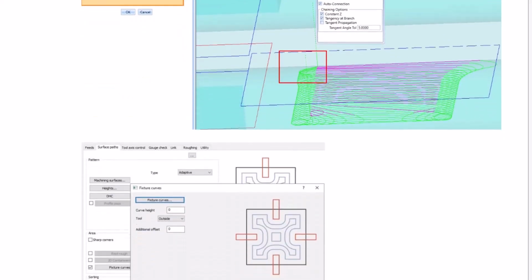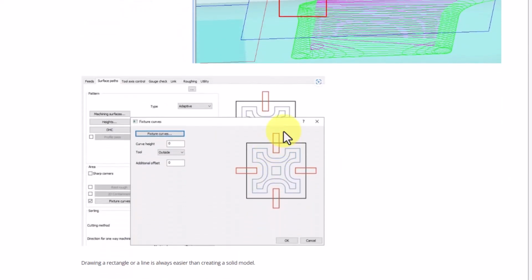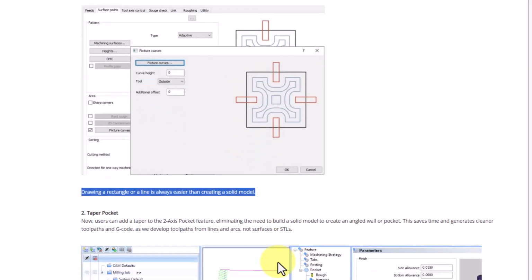It's just faster, simpler. And this works for both 2-axis pocketing and the 3-axis Pro features. You just sketch your boundary, tell BobCAD don't go in here, and it prevents those costly collisions. Saves time, saves potentially scrapping a part or damaging a tool.